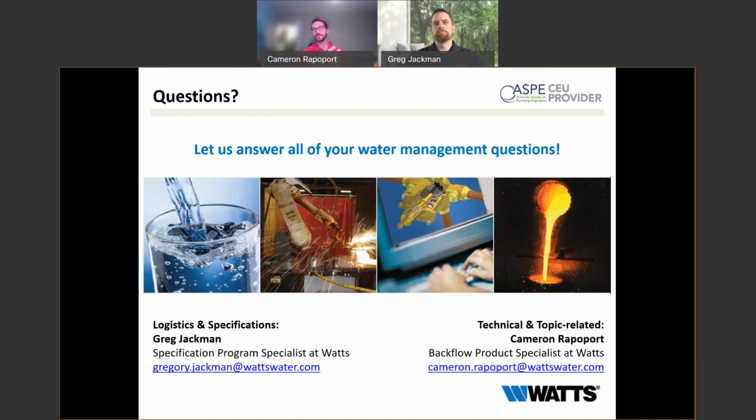So if you have an FDC and there's a pond right next to it, that might make your local code official want to upgrade that to a high hazard because of the potential of a pump truck hooking up to that. Or if there's a well or some other non-potable source right nearby. So it does depend on the surroundings, and again, depends on local code. But just the mere existence of an FDC will typically not make it a high hazard.